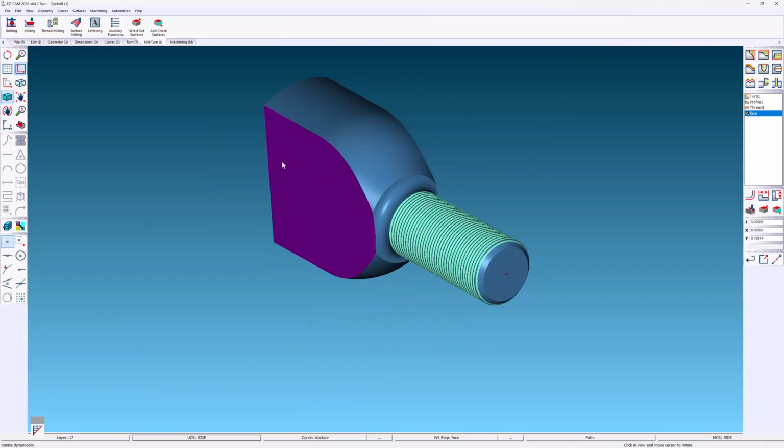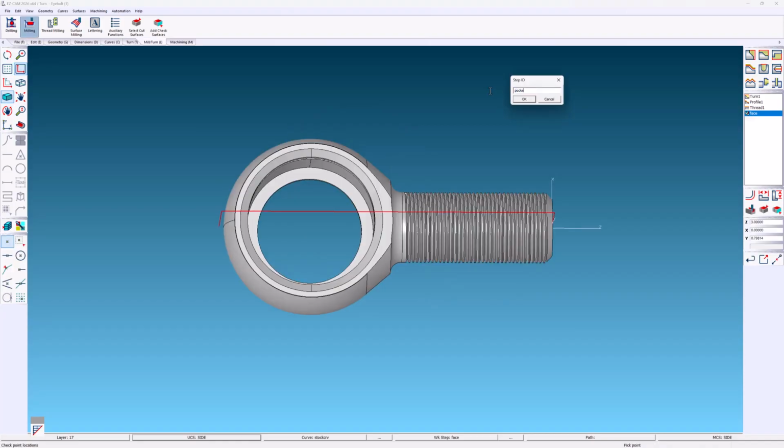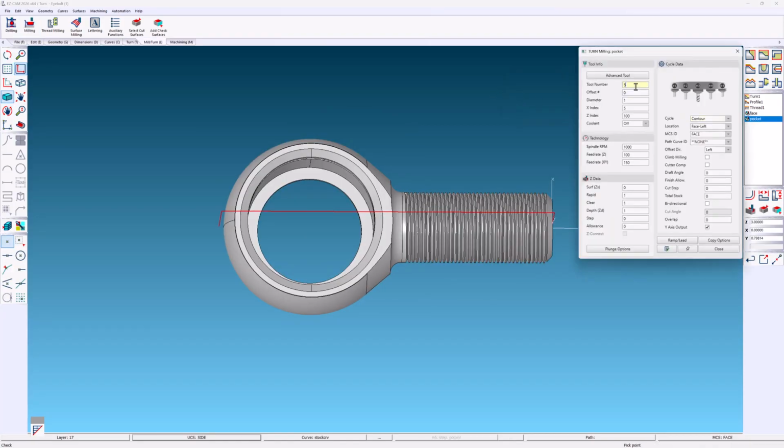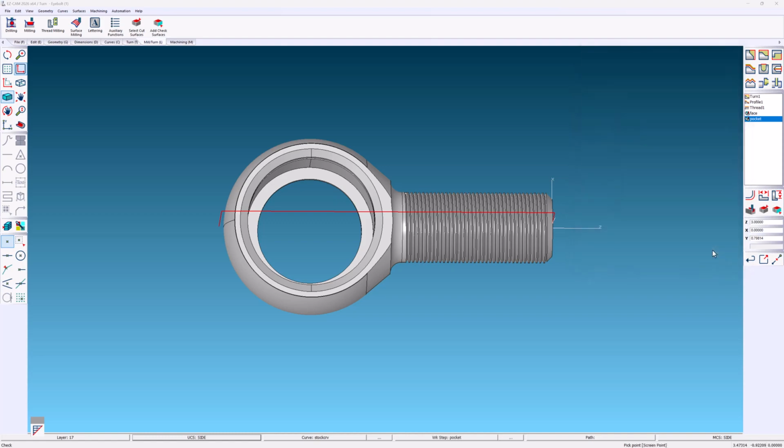Now we will machine the large pocket. We'll use high-speed machining and use the same location and coordinate system. And with that, we will want to include a finish path. For pockets that bottom out, select the bottom face.